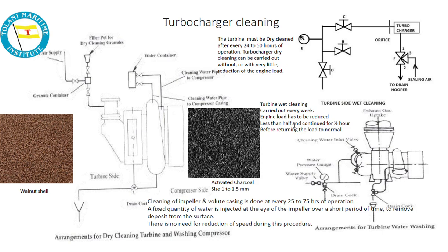The blower side is cleaned by fresh water only. The engine is run at full load RPM. A container is filled, with an inlet line coming from the blower discharge side and an outlet line from the container going to wash the blower side. So this is all about turbocharger cleaning.